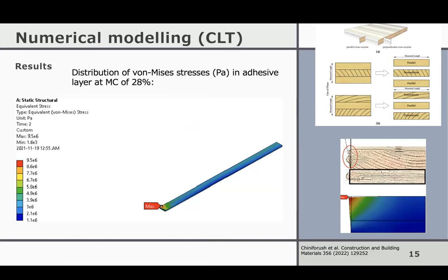And the other thing I should mention is that for the laminated fiber reinforced composites that we use in automotive and aerospace applications, the delamination usually starts at the edges. So we have an edge effect that highlights edges are susceptible to stresses. And we see that here again. That possibility is the same for laminated wood composite because the mechanics is the same.